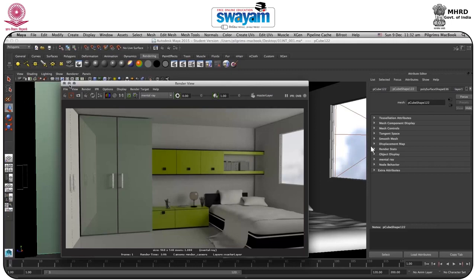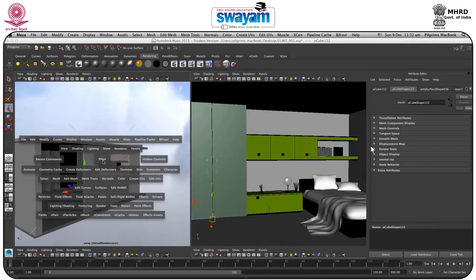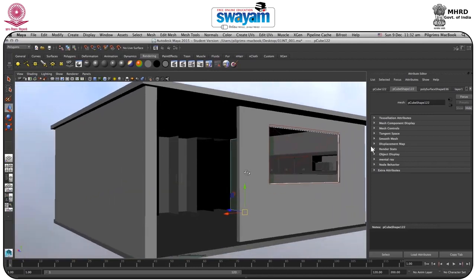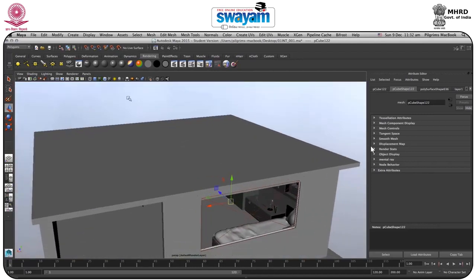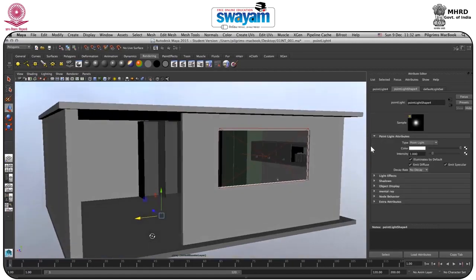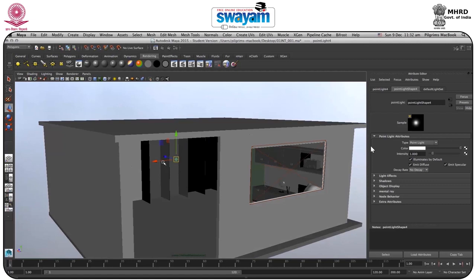And okay, so we'll not glow this thing because it's morning and we don't require to glow all the things. So we'll just click this off, and we'll make some more lights for a little bit of bounciness. What I will do, just go to the Omni, which is the point light, click the point light, and we have just drawn the point light here, and we'll move it around here. We'll make sure that you're saving your file because saving is very important.